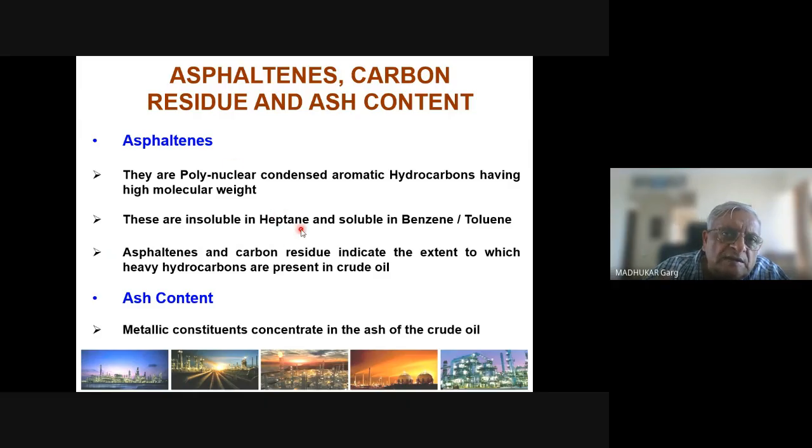So in many of our discussions in the industry, we ask how much is the heptane insoluble. What exactly we are referring to is the asphaltene content. Okay, and besides asphaltenes there's another characteristic called carbon residue. So both asphaltenes and carbon residue indicate the extent to which the heavy hydrocarbons are present